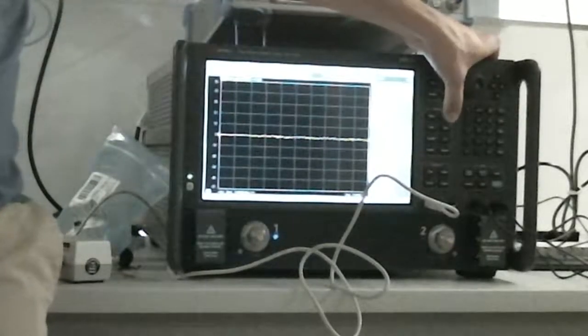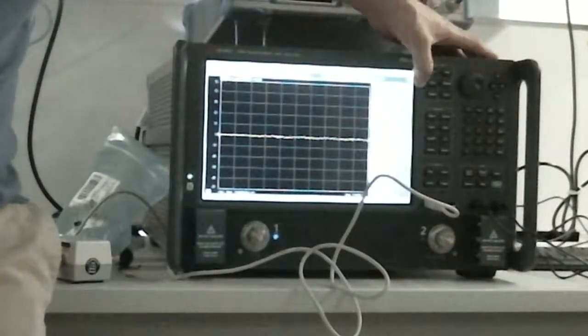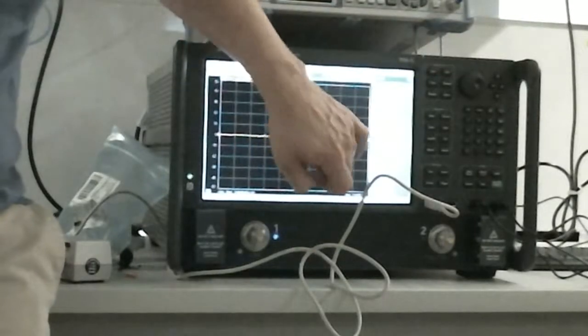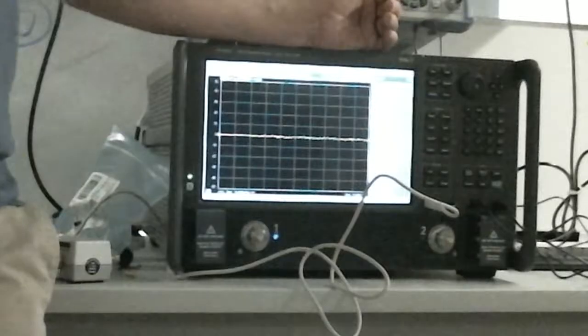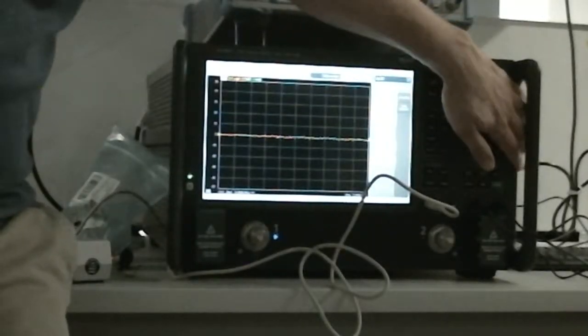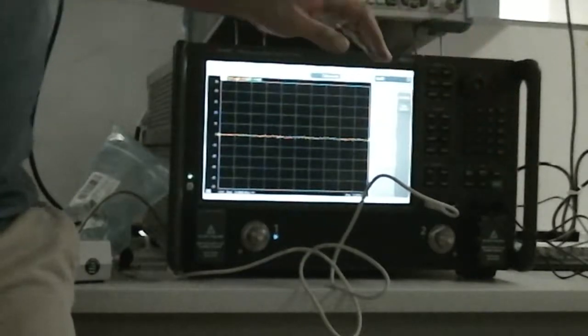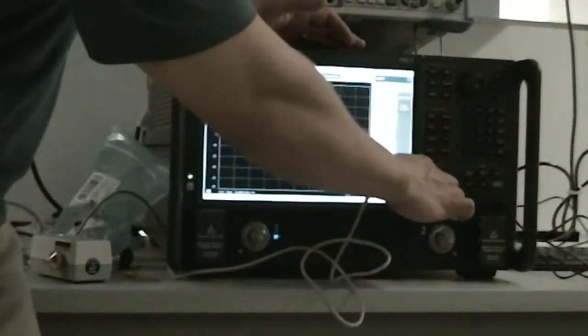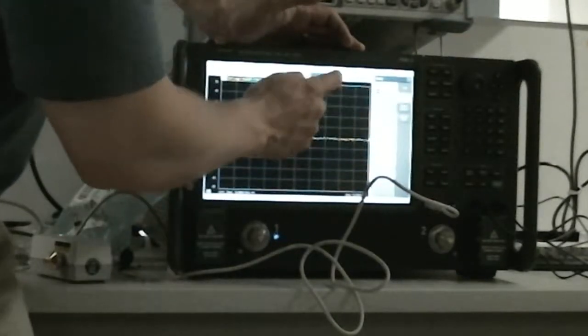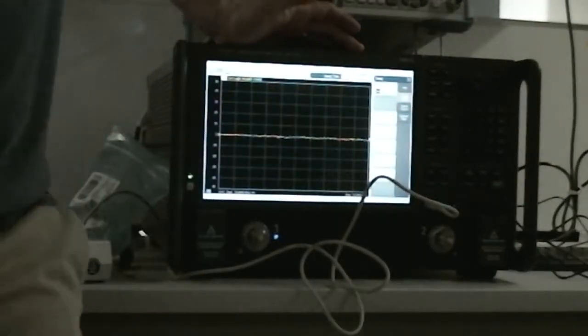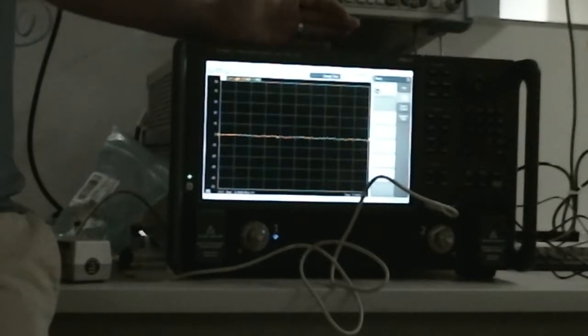So what I'll do is, you'll see under my IF bandwidth, it's usually by default when you start it up at 100 kilohertz to optimize the measurement speed. So we're doing the full span from 10 megahertz to 13.5 gigs, and we're doing 201 points, and you can see if I go to sweep timing, this takes about 1 millisecond to do the sweep, right? So very, very quick.